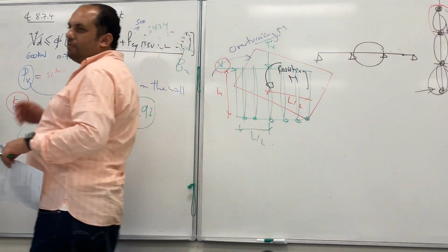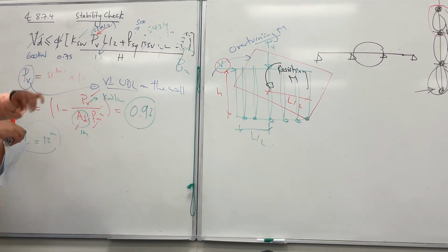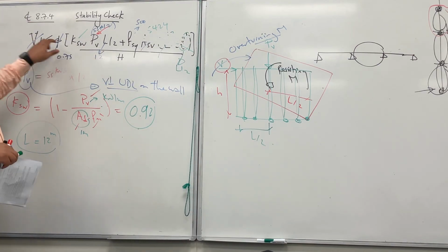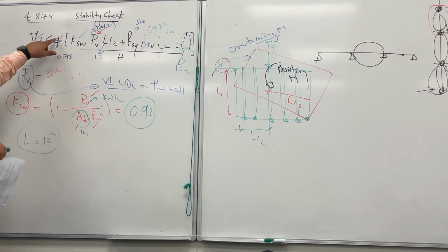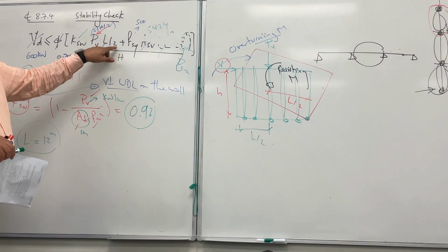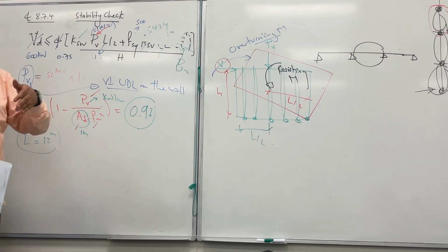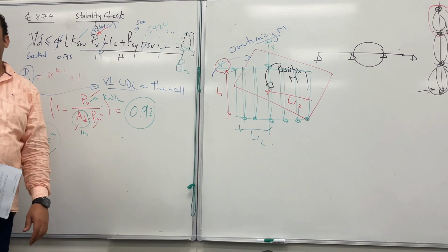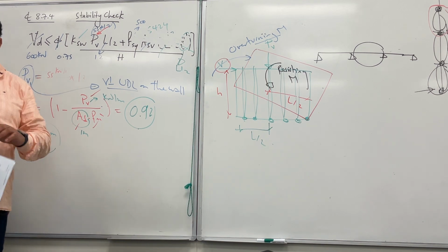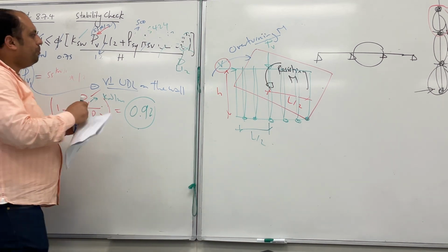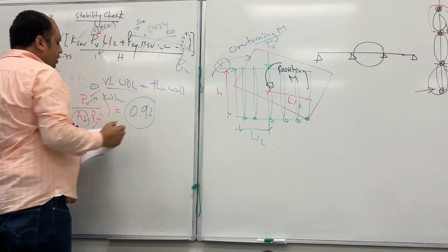So, do you understand what this formula is? The formula says the overturning moment should be less than the resisting moment. So the steel, if the centroid is in the middle, doesn't add any resisting moment to the calculation. Okay? So this term will be 0.